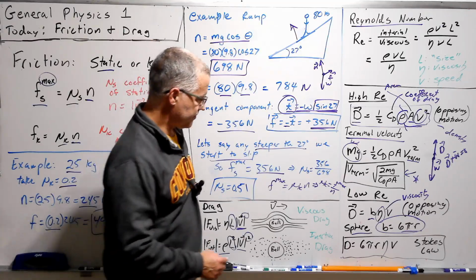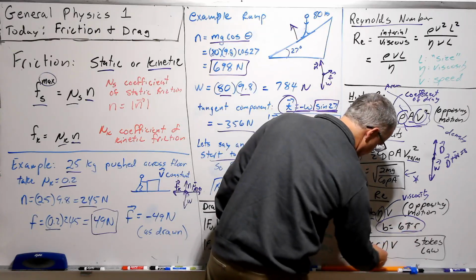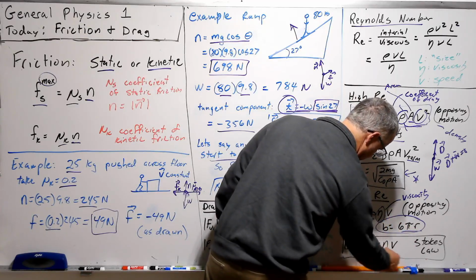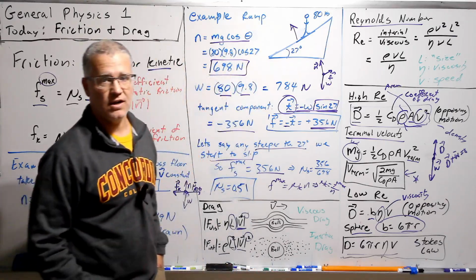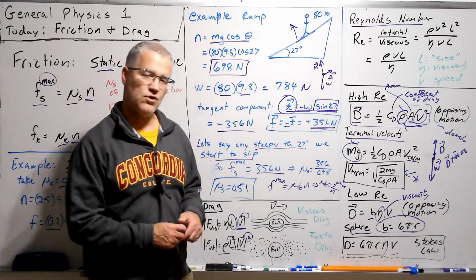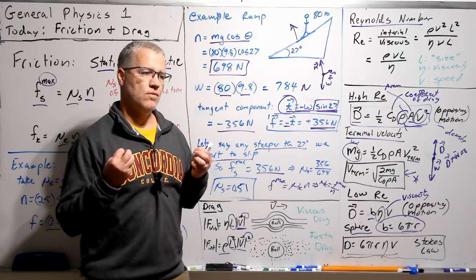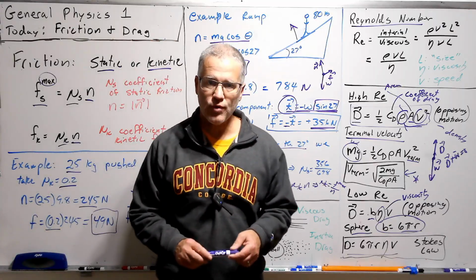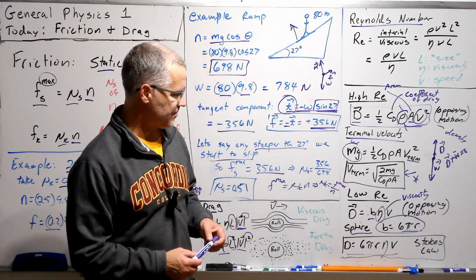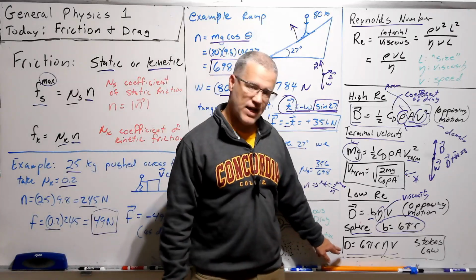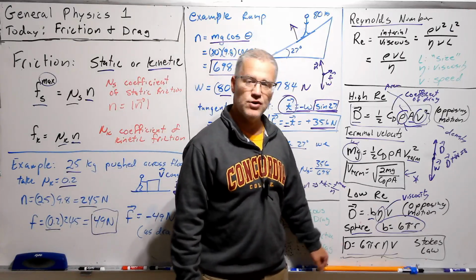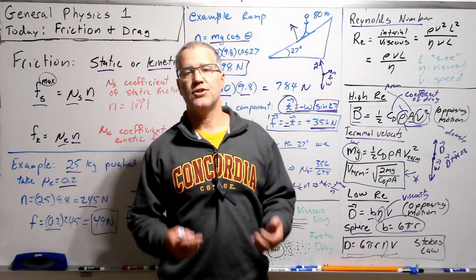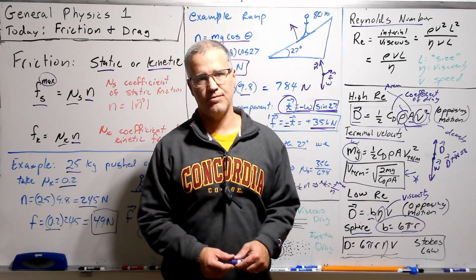If we plug that in for this limit here, we get something called Stokes' law. Stokes' law shows how a ball or a sphere moving through a low Reynolds number fluid will behave. And maybe you can pause the video now and set this equal to mg and determine the terminal velocity in the low Reynolds number limit.